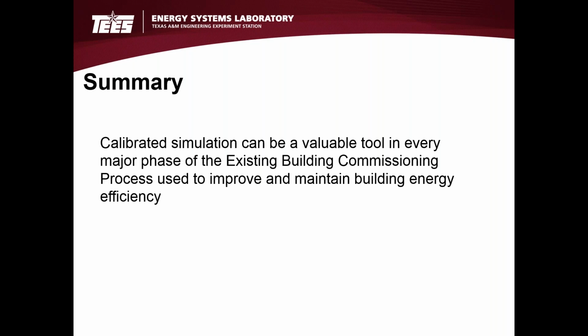So in our experience in the calibration process, particularly for the commissioning process, we generally are not highly concerned about detailed building dynamics, but rather longer-term operation over periods of days, and that tends to be adequate, and hence we use very limited information about the envelope inputs in these buildings.